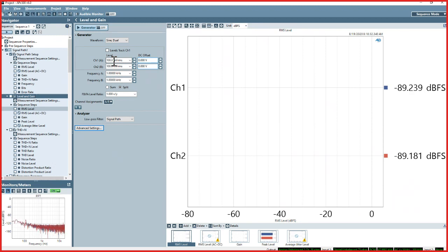However, in some devices, you provide one clock and then the device uses that clock to synthesize and return a different clock. In those situations, a buffer is not particularly going to help you because what you're going to run into is what we refer to as clock in to clock out delay, which is the absolute amount of time you have from when the device receives a signal to when it needs to turn that signal around.